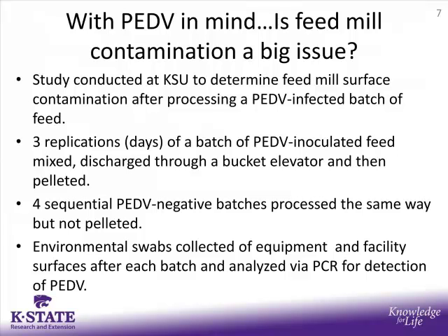And so we conducted this study with 3 different replications, which we'll consider days, or 3 different runs through the system of a batch of PED-inoculated feed, which was mixed through a mixer, discharged through a bucket elevator, and then subsequently pelleted. And then, similar to a commercial mill, we didn't clean out the equipment, but we followed it with 4 sequential PED-negative batches to determine how much cross-contamination could happen from batch to batch. But also, we were able to take swabs of the environment to determine how much overall PED contamination happened within the mill after a PED-positive batch of feed was produced.